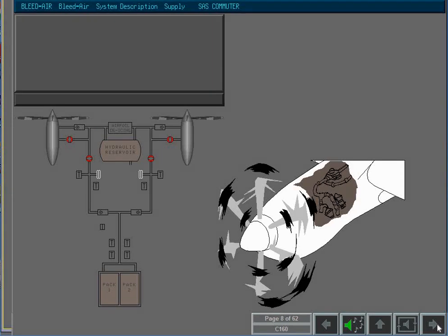The changeover of bleed air source from low pressure to high pressure, or vice versa, is automatic depending on engine power setting. Under normal flying conditions, bleed air is used from the low pressure source. At low engine speeds, for example when power is set to flight idle, low pressure bleed air is insufficient to supply the consumers, so high pressure bleed air is used.